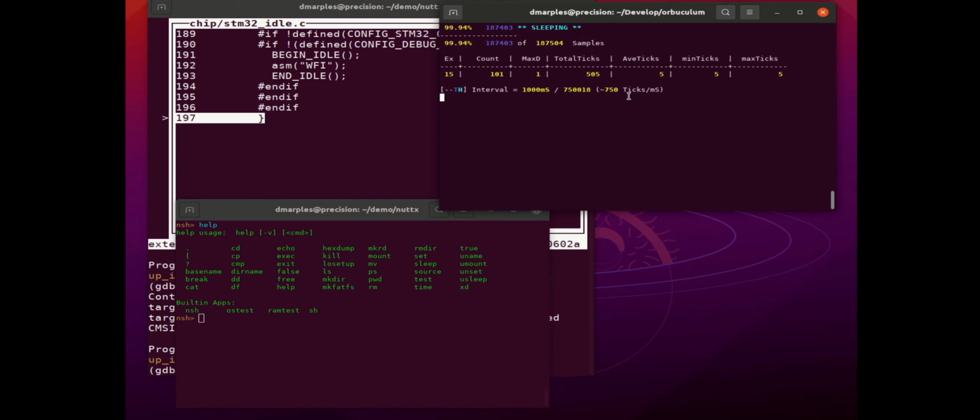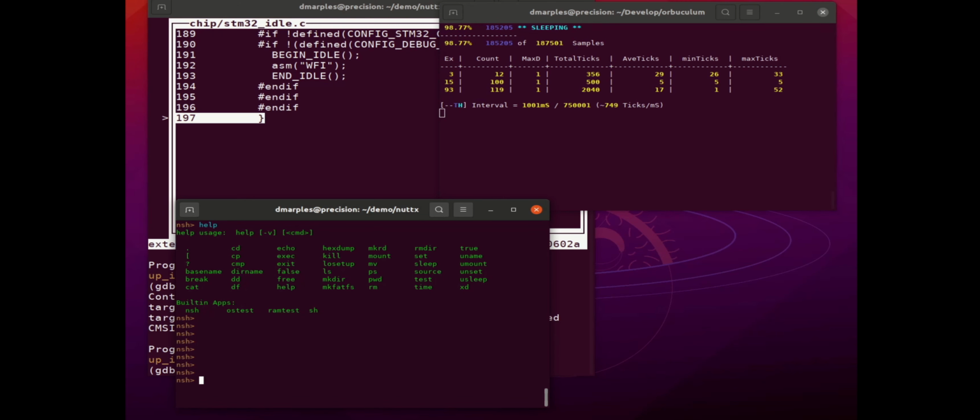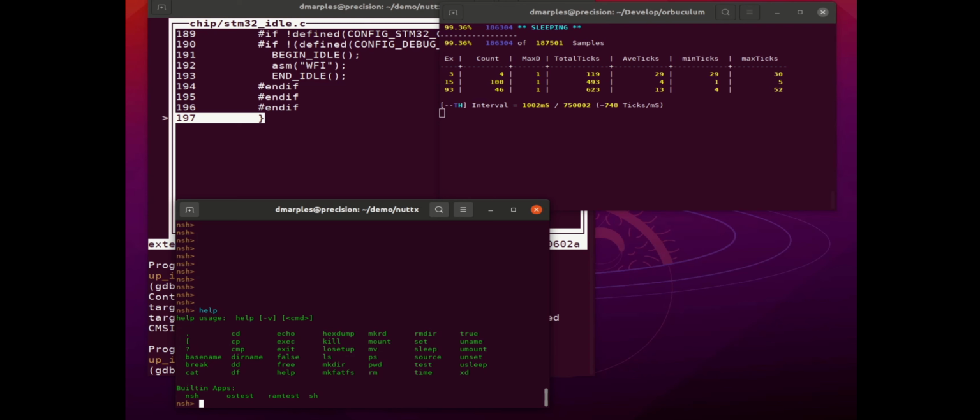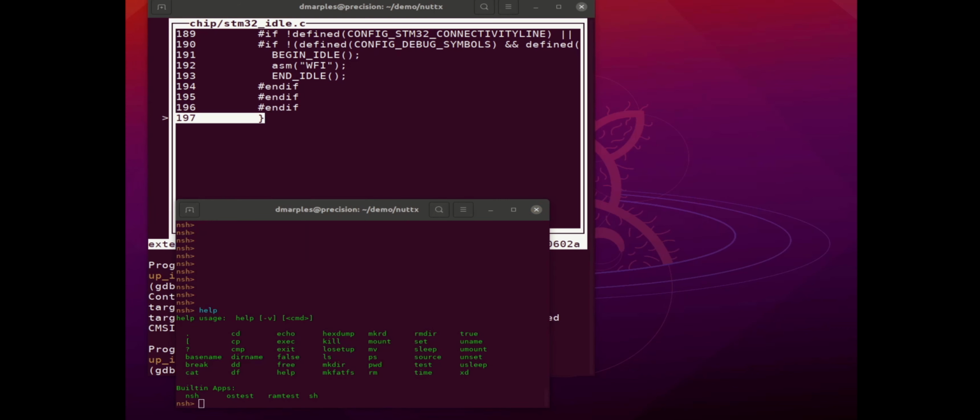It makes perfect sense. If I start to give the thing a little bit more work, we've now got USB interrupts and all sorts of other bits and pieces, and we can start to see those other interrupts occurring in the table. So again, more work, and you start to see it appear in the orbtop output. However, it would be really nice to go into more detail than that and see the detail of what was going on with the instructions, and that's where the new tool, Orbmortem, comes in.